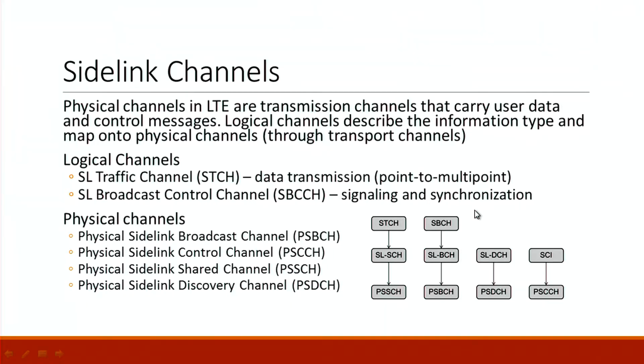logically different channels called the transport channels and the logical channels. The transport channels deal with what type of packets you are using, whether you're using small packets or big packets for the information traveling on that channel, whether you send these packets frequently or just once in a while, for the communication happening in that channel. The logical channel tells you what type of information you are sending. So you see here, this is specifically for side-link channels.